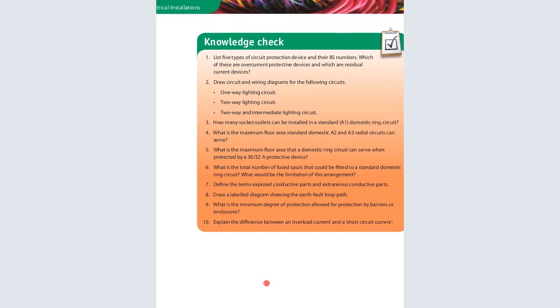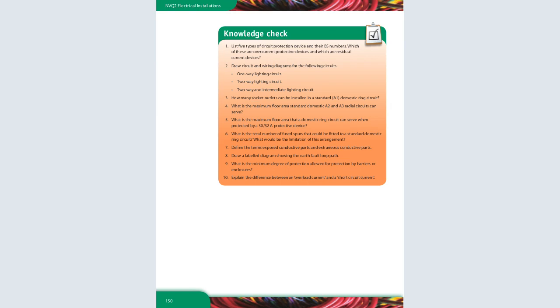But when you are also doing an installation as an electrician, you also have to do the earthing from the consumer unit end. You have to supply the customer with the earthing. That is, the earth wire has to be connected to an earth rod and driven to the ground. So the earthing has to be both ways to maximize the safety from any risk.